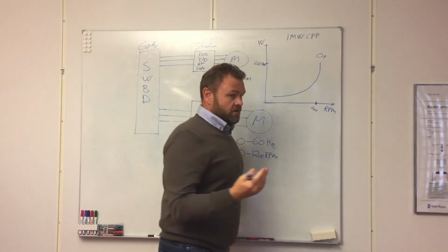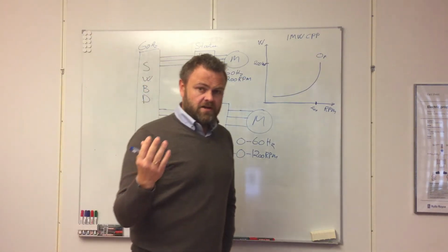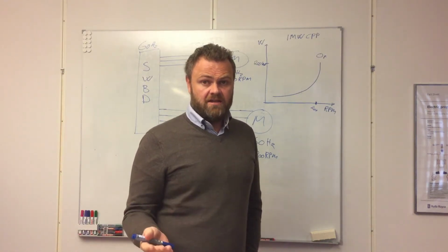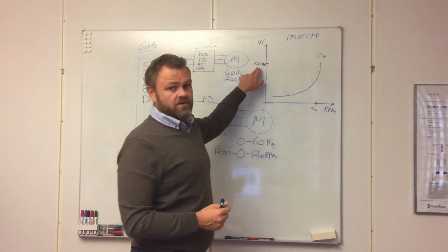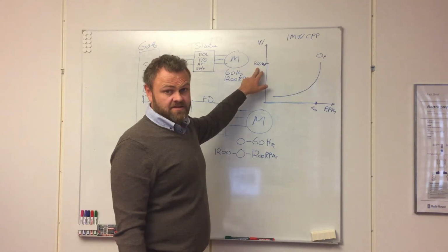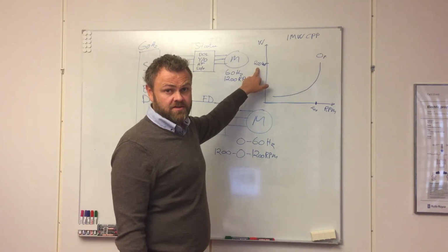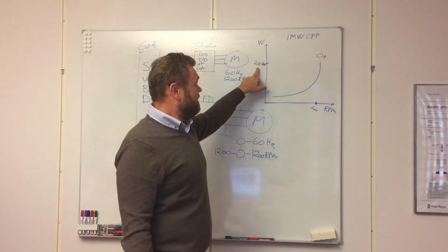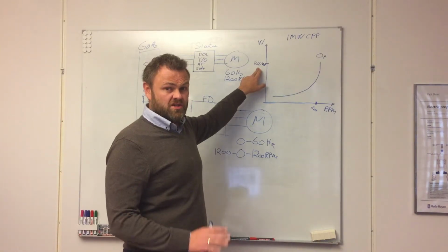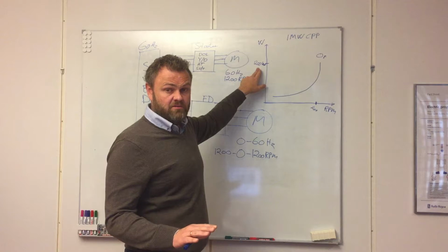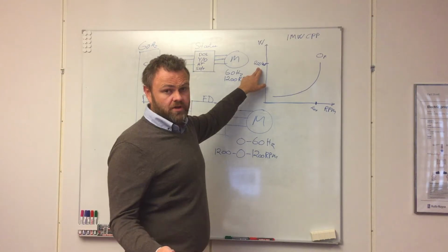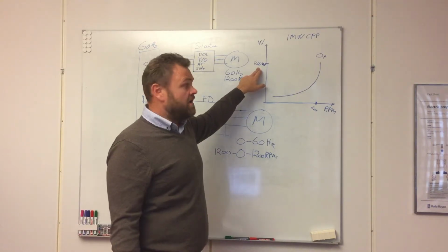So for a typical offshore vessel where this propeller is running for many hours every day, this loss of 200 kilowatt, let's say he has several tunnel thrusters, maybe 5, so 5 times 200 kilowatt just due to idling around is 1 megawatt in loss. 1 hour is 1 megawatt hour in loss.